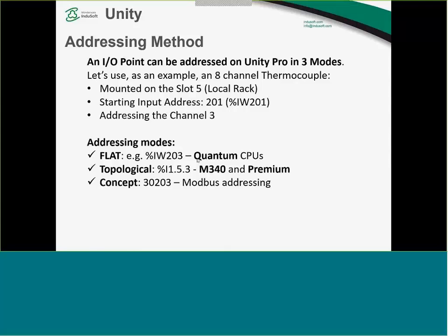That's a flat communication. But the M340s, for instance, use the topological address, where you put %I1, dot, the slot number 5, dot, the channel number 3. Okay? And using the regular Modbus, or what we call the concept addressing, it's going to start with 3 because that is an input. It's going to be 30,203. So you have the offset against the 201 from the start input address.